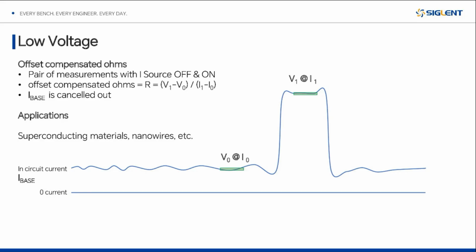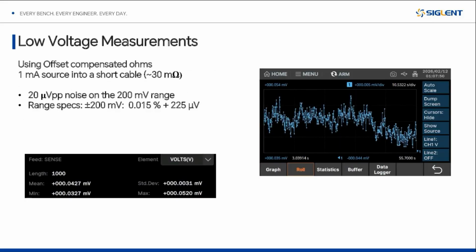And we look at the differential, the changes in the current over the changes in the voltage, and that gives us the accurate resistance measurement: the differential voltage divided by the differential current. So that's a great way to really get a little further and eliminate other environmental issues or fixed currents and voltage that are impacting your system.